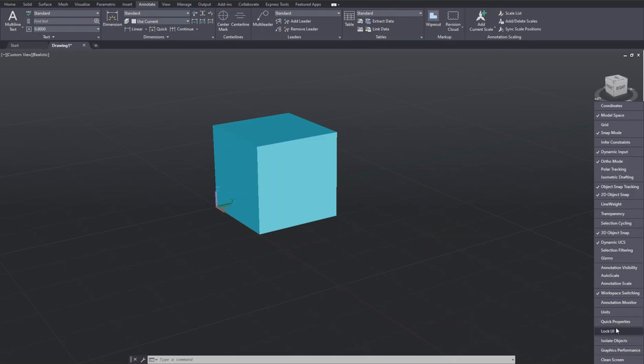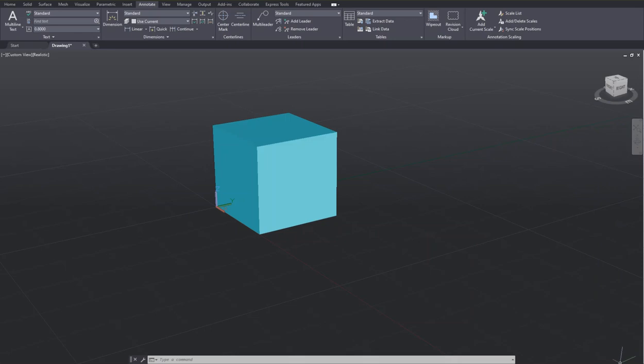These are all the necessary tools, and they enable you to see the settings. For example, this particular setting is very important in 3D applications. Dynamic UCS picks the surface that your cursor is close to, and it automatically moves your UCS there. So let's see the effect of it.